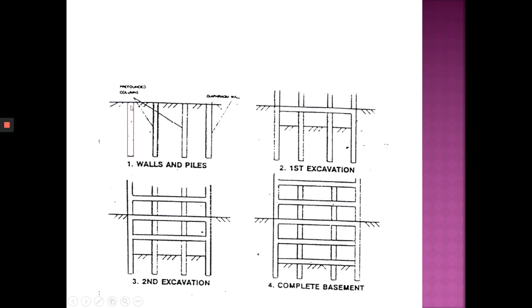Okay, the first thing is just the cut and cover now. I think cut and cover, you have the retaining wall. So on the illustration, it says diaphragm wall. So you can either use diaphragm wall, secant pile, or contiguous bored pile. For top down, they don't really use soldier pile or sheet pile. Why?